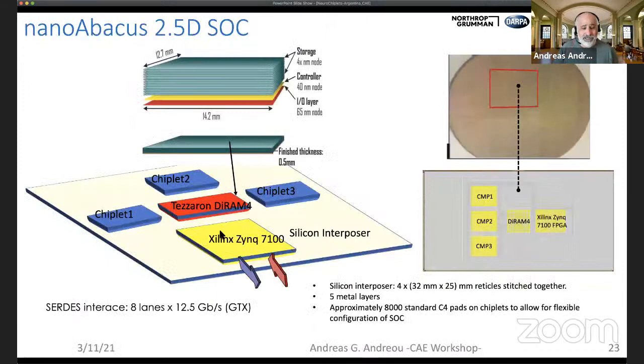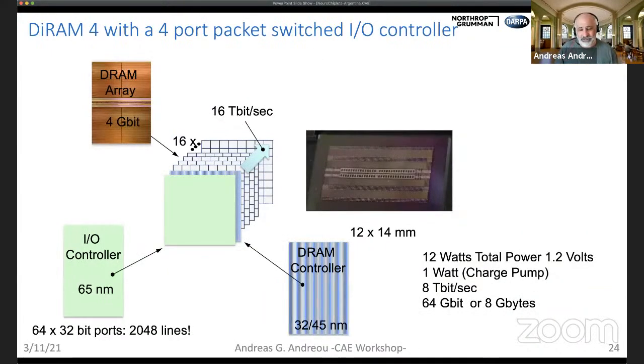So going back to the architecture, imagine now having a system with 8 gigabytes of cache memory, because effectively that's really what you have here. You have the memory integrated on the system. Unfortunately, the sad part of the story is that the company that used to make these devices could only make 1 or 2 or 3 experimental ones. They actually did, and this is a real picture of the device they fabricated. Eventually the technology was sold to Hynix, along with the intellectual rights, and to Samsung, who now reliably produce the HBM architecture.